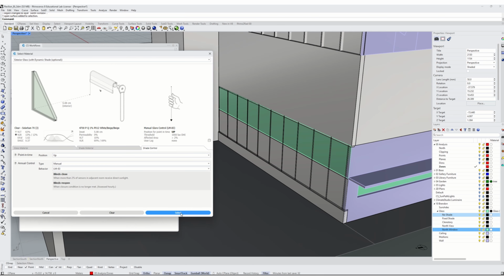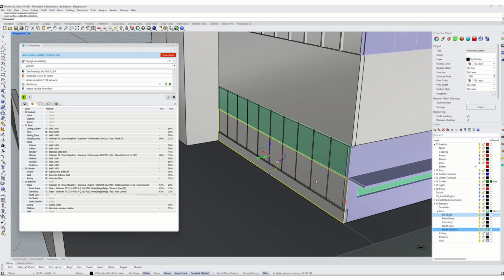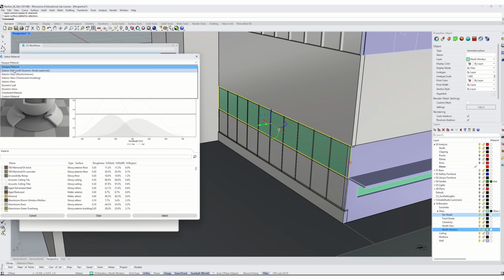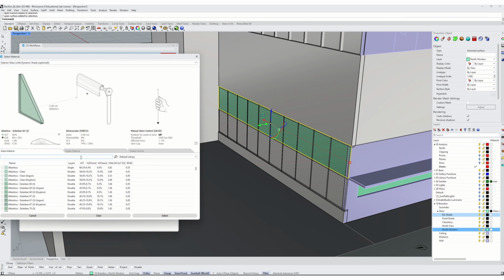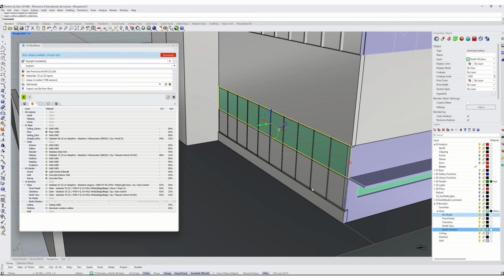Because we have this light shelf, though, this manual control and this manual control should hypothetically be different. We'll see how this turns out. Hopefully I don't have to redo this tutorial. So let's see, I did the north view, now I need the north window. We're going to set this to be exactly the same so we can see the difference between the two. Manual. There. Okay.